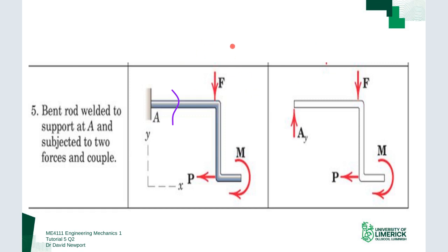And just remember that for all your equilibrium problems, you draw a free body diagram. And in the exam, there's a chunk of marks going for doing good free body diagrams. They don't need to be a work of art. They just need to be the object in isolation. So there's no surface shown here or any of that nonsense. There's no cables connected onto it or anything like that. Just the object in isolation. And instead of contact, you show the forces. And again, just indicate your coordinate system. That is always good practice.